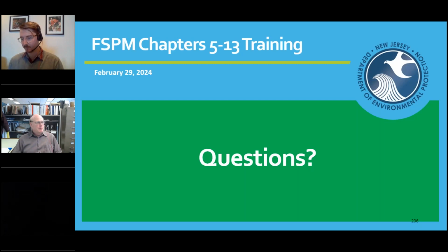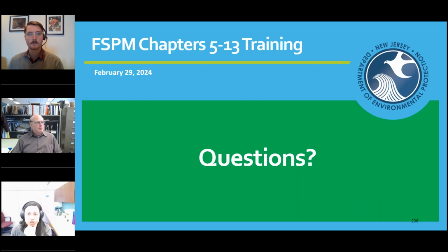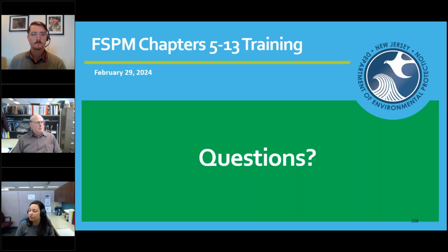Okay, and the next question is, Kyle, hold on, sorry. I'm just going to jump in from the permit perspective on that question, since that's probably what a lot of people are thinking about with that question. My name is Alyssa Ambacher. I'm with the Bureau of Remedial Action Permitting. And as far as the volume average purge sampling goes, we know there are a lot of sites that predate the Field Sampling Procedures Manual, but like Greg said, we do expect to see that volume average purge sampling happen at the site. If you haven't done it, you should definitely justify in whatever document you're submitting why you didn't.